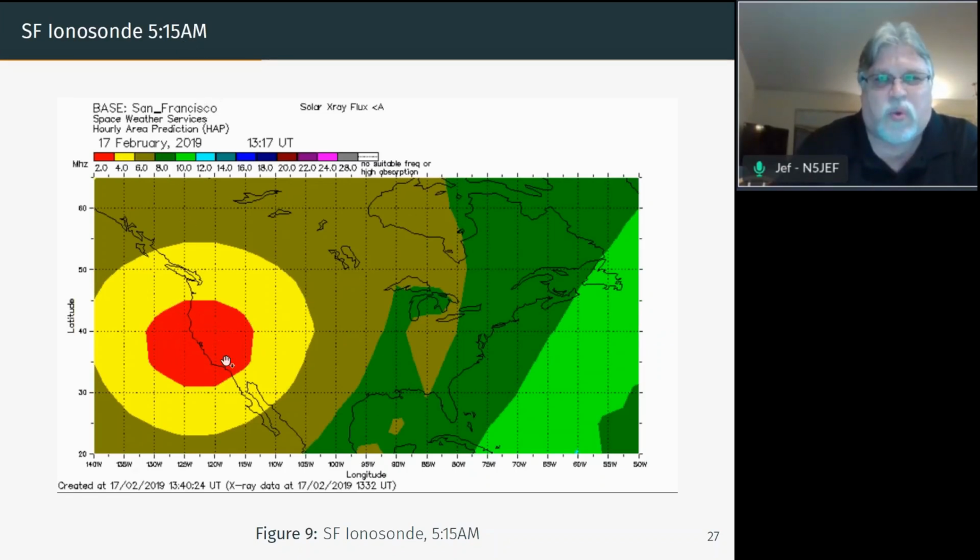And you can see this red here shows that the ionosphere is not very charged. Even 80 meters, which would be 4 megahertz, even that has gone long. And really, if you want to have reliable communications locally, you might want to use 160 meters. 80 meters will still work, but not as efficiently as you might want.